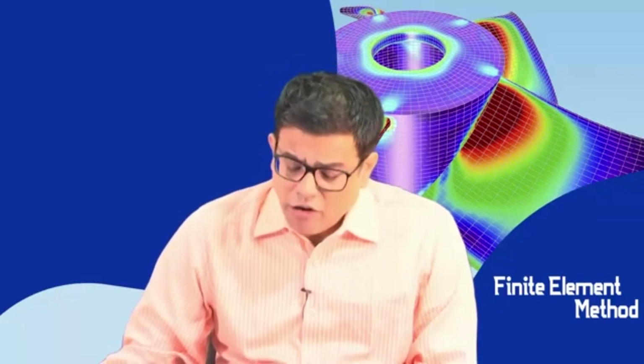So the basic assumption is that dw dx, the derivative of the displacement interpolation, should be equal to the theta interpolation in the case of a thin beam. To achieve that, we did consistent interpolation, which is a different order of interpolation for displacement and a different order of interpolation for the